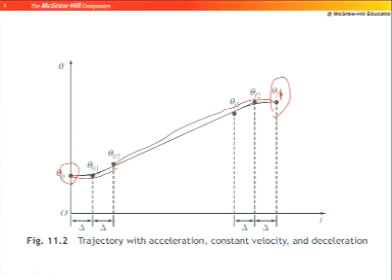Why is this so? The reason is I want to start with a 0 acceleration here and I want to finish with a 0 acceleration here. For some reason I do not care what my f should be, there could be some velocities. Okay. So, how to do this kind of trajectory? This is one of the standard trajectories used in industries.